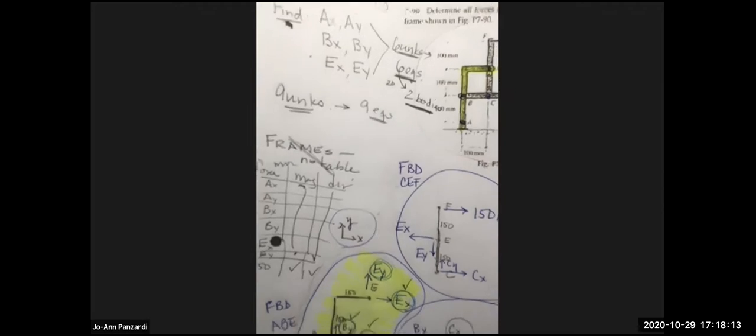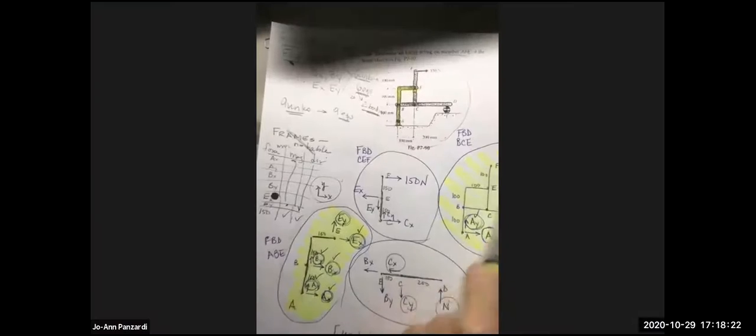All right. So after we did the given and find, we always draw a free body diagram of the whole structure. The reason is that so many of the forces are internal. They drop out and we could find some forces. We also do a free body diagram of the main body that they're asking us about because we're going to need to know all of those. And then you can do another free body diagram, but you have options here.